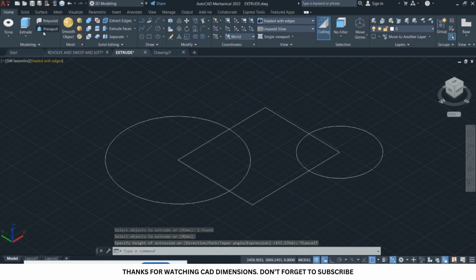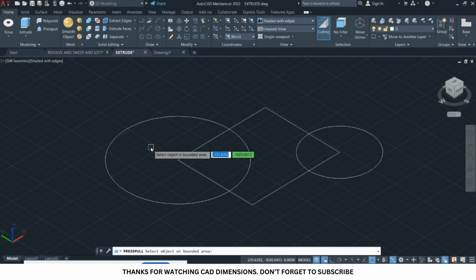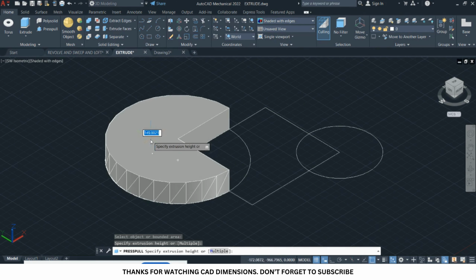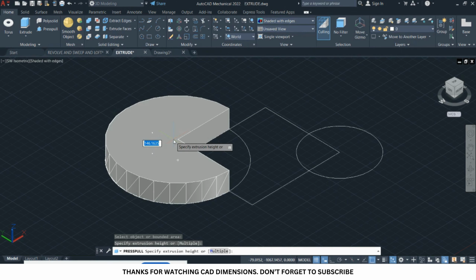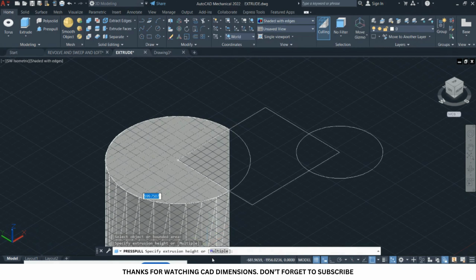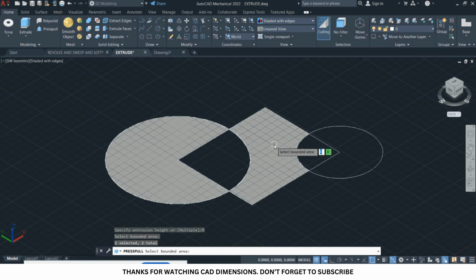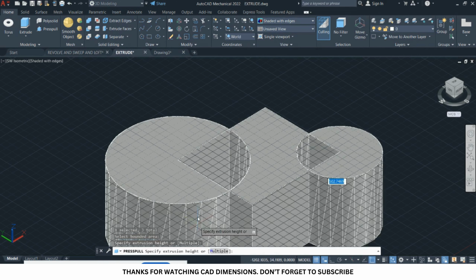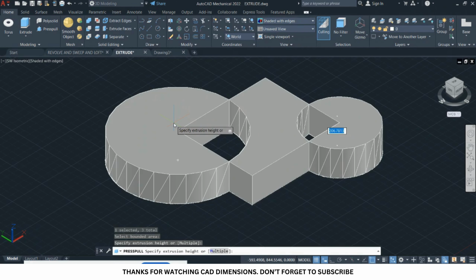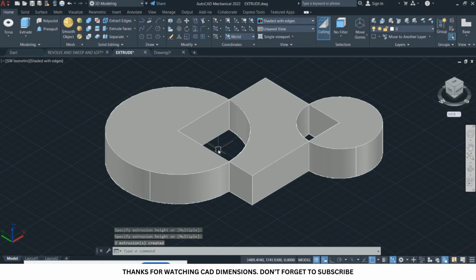For the press pull, we've looked at it, we've practiced it severally, and we know that the press pull does the selection with respect to region. Okay, so the bounded region is where it extrudes. Another thing with the press pull is that you can do multiple selections. So if I click on multiple, I select multiple regions that I want to extrude. Once I'm done, I press enter, then I'm able to extrude that.